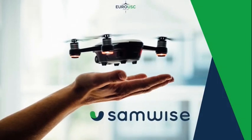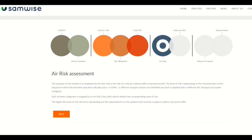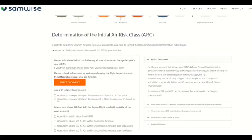In the previous video, we have seen the ground risk. Now we proceed with the air risk class. We start by clicking Next. Okay, so for the air risk tab, there are a few parameters to take into consideration: the airspace where the drone will fly in, the height of the planned flight, and the operational environmental characteristics.